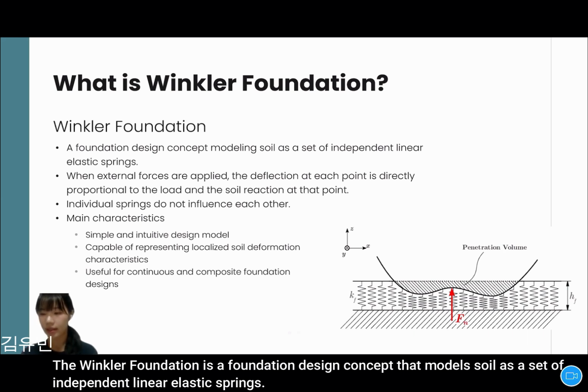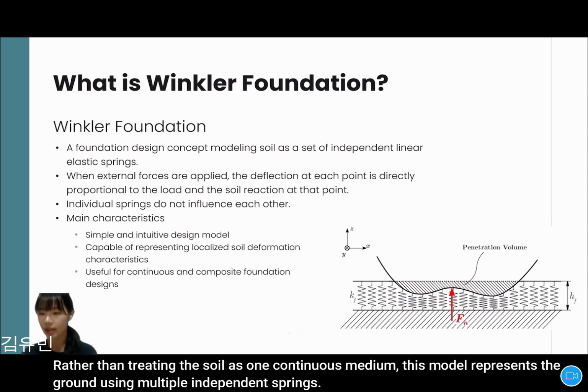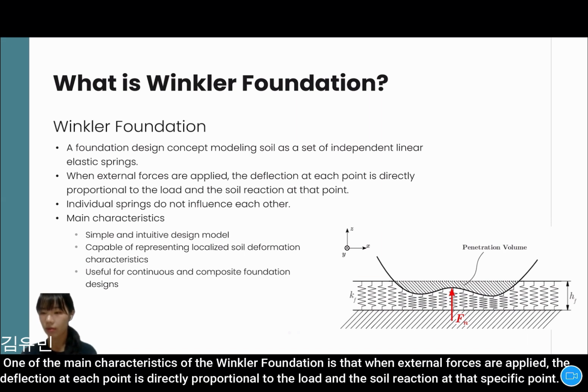The Winkler Foundation is a foundation design concept that models soil as a set of independent, linear, elastic springs, rather than treating the soil as one continuous medium. This model represents the ground using multiple independent springs. One of the main characteristics of the Winkler Foundation is that when external forces are applied, the deflection at each point is directly proportional to the load and the soil reacts at the specific point.